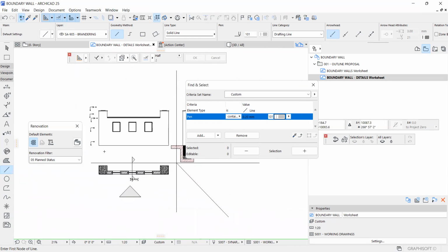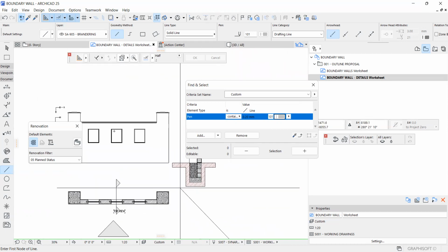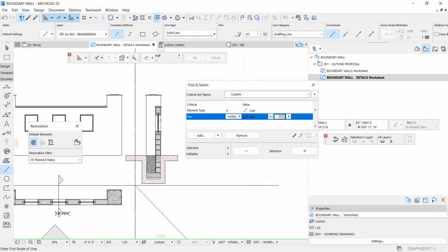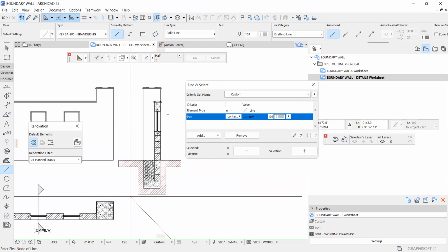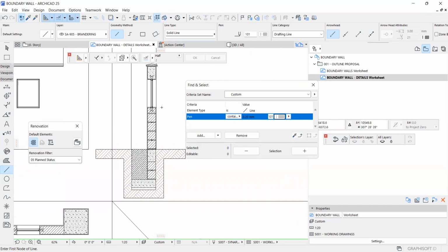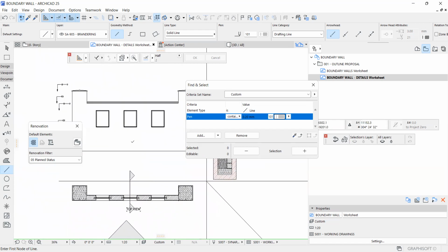So as you can see, we have our plan, we have our elevation, which is projected, the front view, and then we have our section, which is a side view, projected, okay? So this one I've deliberately done to assist you both in drafting and to also assist you in our studio work, because now when it comes to modeling, this section will be very critical, because you just pick up what you have done here and replicate it and use it, okay?